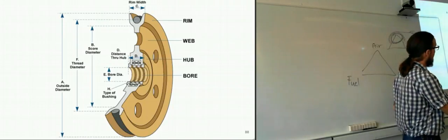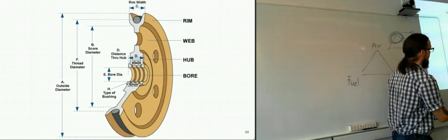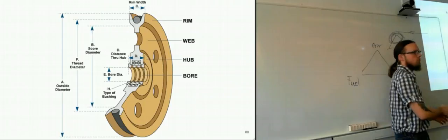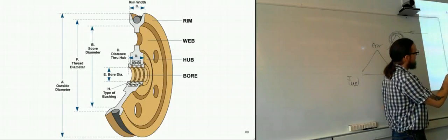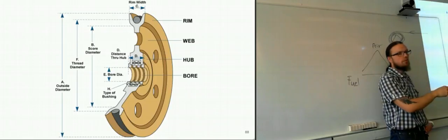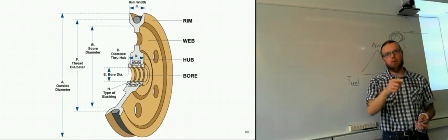So using these sheaves, not only do you minimize wear and tear, because instead of being dragged along the surface, it gets to roll. So the wire itself stays in contact with the same area of the sheave along the entire rotation that it does around it.